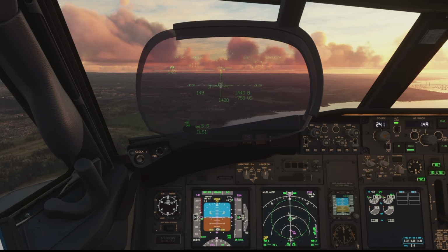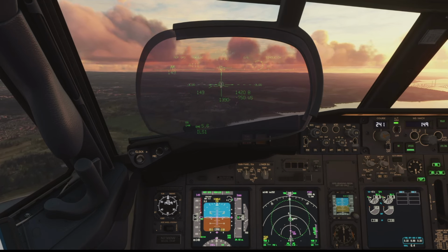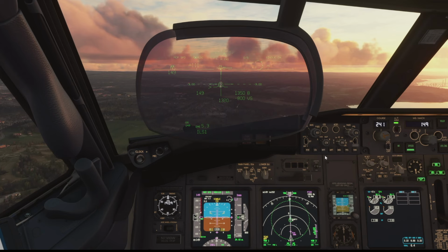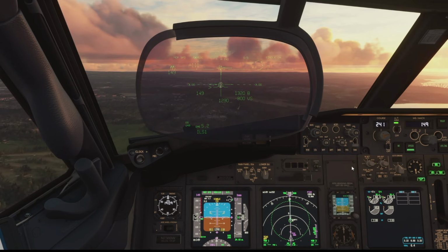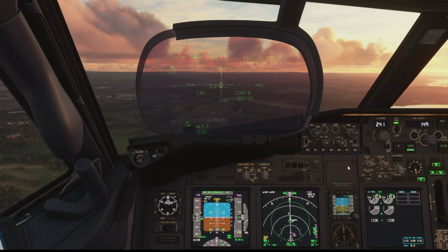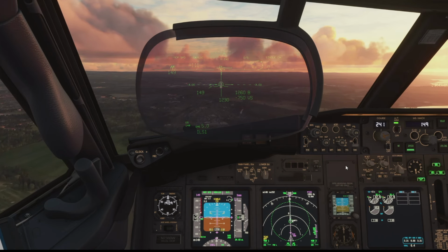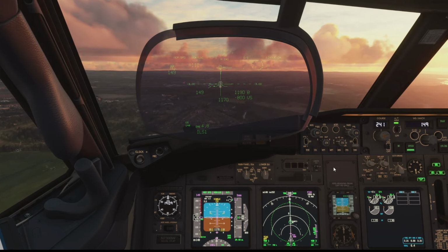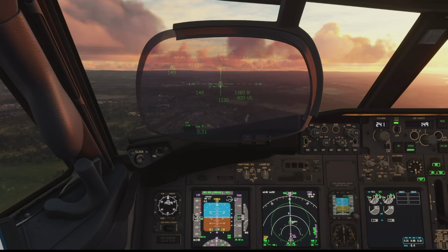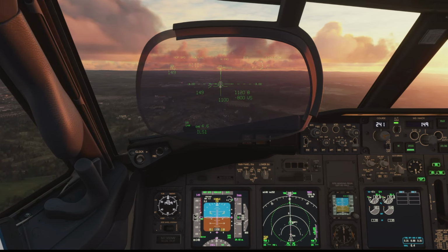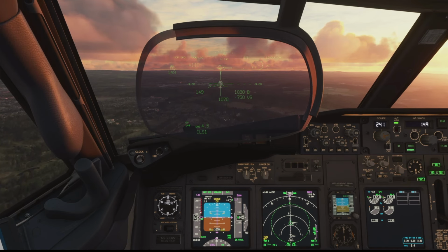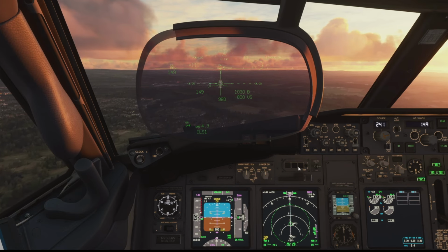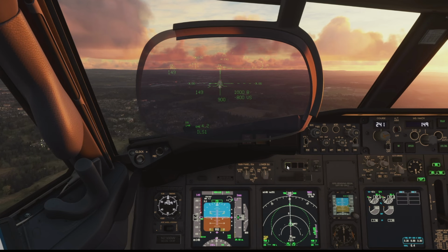Okay, so continuing to monitor all those readouts then, everything's looking pretty good speed wise. We're now 5.4 DME from the runway, just passing through 1,300 feet, and I will disengage the auto thrust and autopilot around about the 1,000 feet mark and hand fly our landing. And we have 2 whites and 2 reds on the PAPIs, and you can see that 3-degree glide slope line passing right through there, so that tells us we're bang on profile as well, so that's good. And auto thrust disengaged and autopilot disengaged, and my controls.